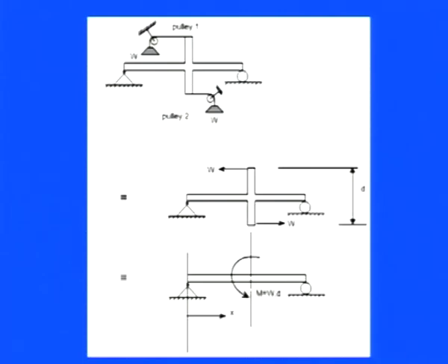to balance that. Or if you want to compute those things, if you just replace these pulleys by these forces, we have a force in this direction and another force in this direction. And when you have this force and this distance, you can simply compute the moment, which is nothing but force into distance. So this moment will be acted at this point. This is the exact axis of action through which this moment will be applied, and this moment will be going in this direction. So whatever resistances are coming will be coming in the opposite directions.